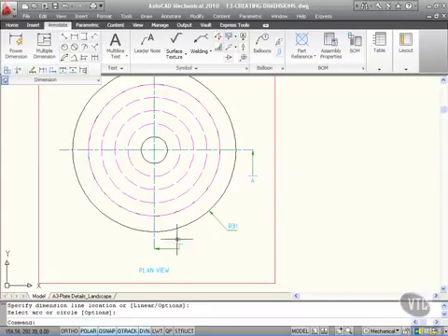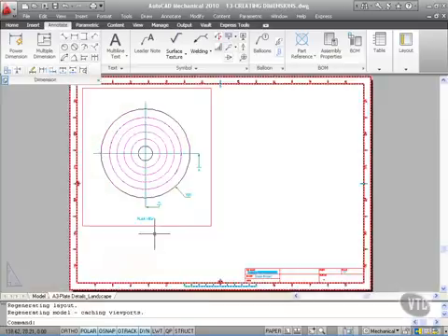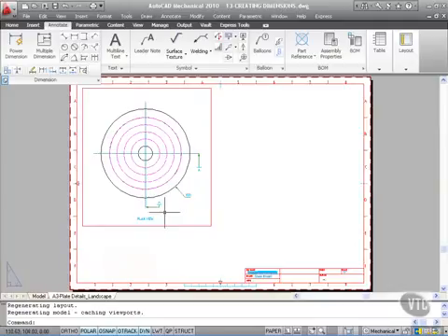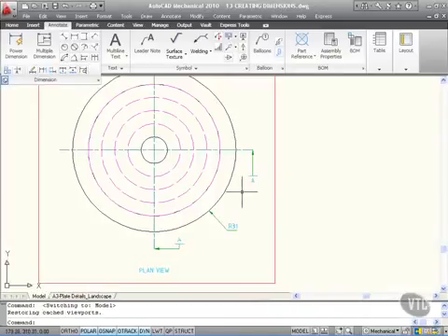Now you'll notice it's adopted text the same height as the scale area. So you can see there the text is radius 31. But look, the A, the R, they're all the same height because we're working in that 2:1 scale area. So if I saved my drawing at this particular point in time and went and looked in the Layout tab, you'll see, look, all the text is appropriate for that scale area, that 2:1 scale area. I'll go back into the Model tab now.